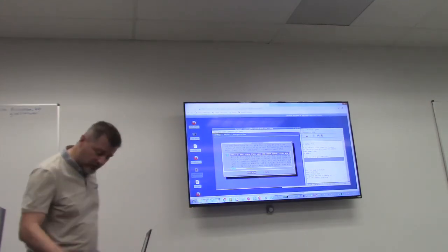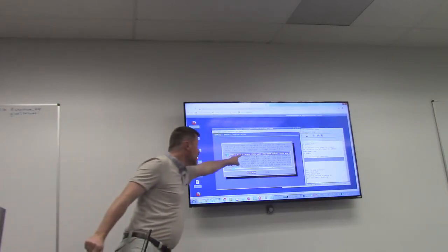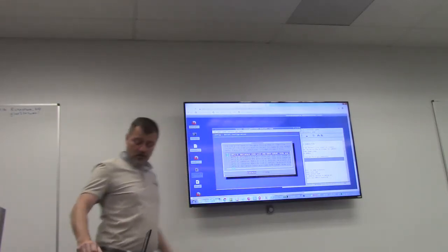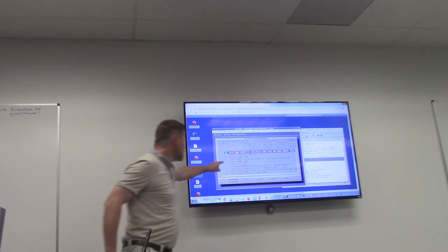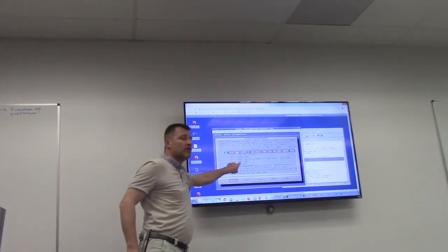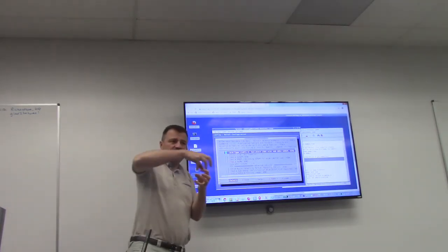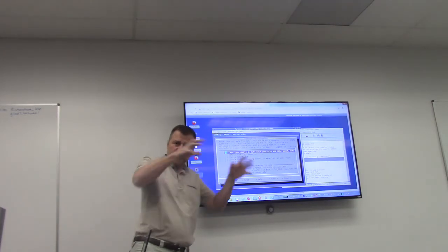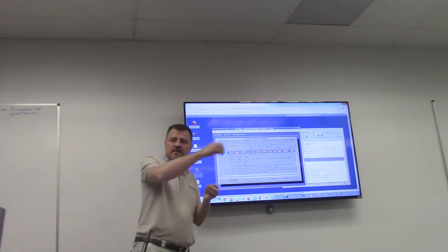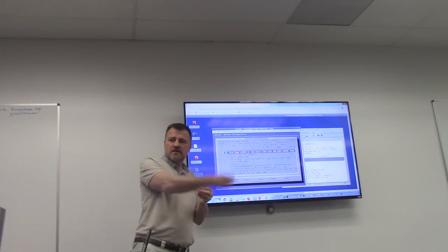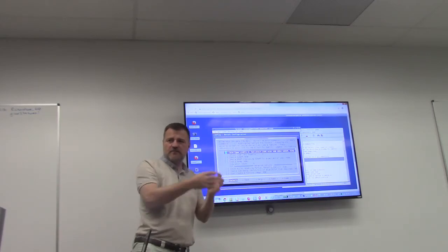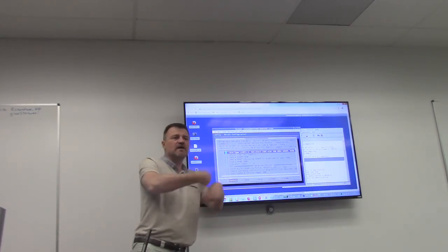And we will select, for example, the Nallatech. This one has an SSD on board. So when I select it, I can enable the driver that will be installed into the FPGA by the Snap tool for you to access seamlessly the DDR on the card. The FPGA can access the DDR on the card to manipulate a file.